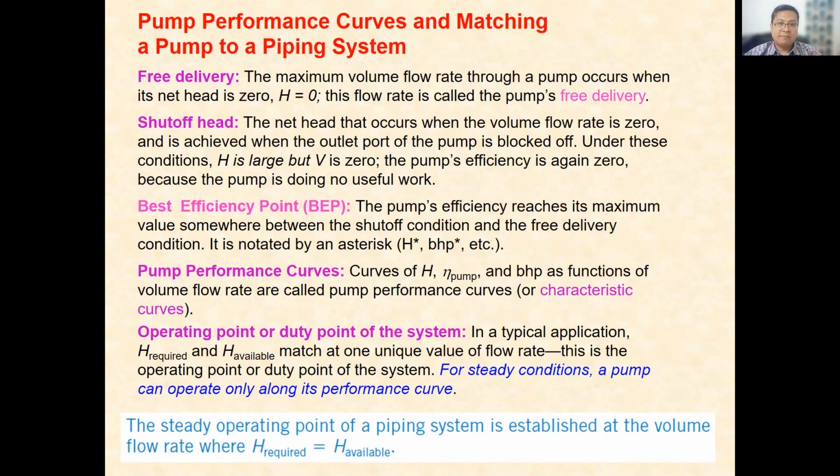So how much available can supply? You can see between the head required and the flow rate, we can make a curve that will cross each other, and that one is the important point. Then we can utilize the number to use in the design.